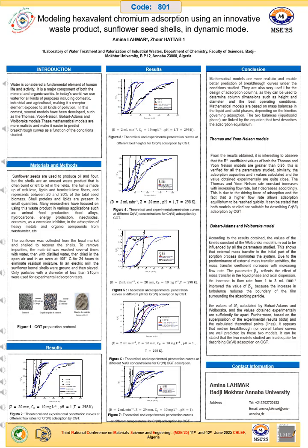Thomas and Yoon-Nelson models. From the results obtained, it is interesting to observe that the correlation coefficient values of both the Thomas and Yoon-Nelson models are greater than 0.95. This is verified for all the parameters studied. Similarly, the adsorption capacities and tau values calculated and the value obtained experimentally are quite close.